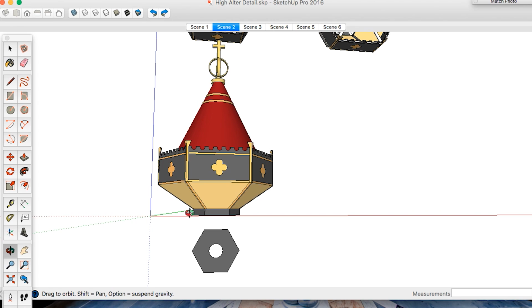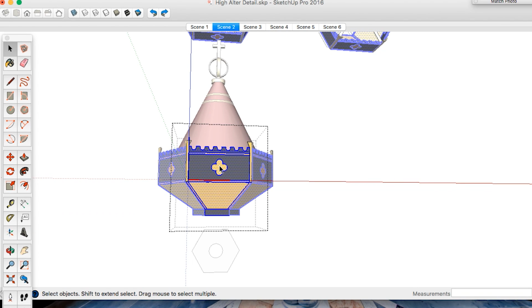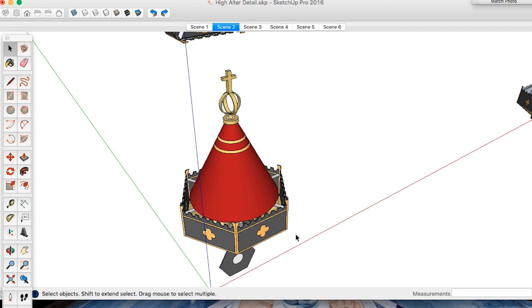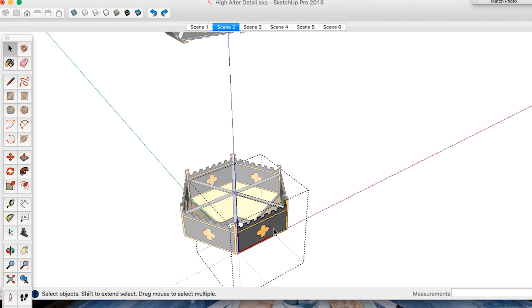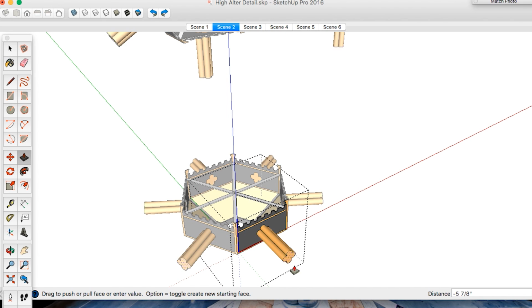As we created this, it certainly wasn't the first version of this. A lot of times we'll take this as a start and just move and copy and make unique, move and copy and make unique. That way you have 5 or 6 different versions, and then you can select the one that works. In this, we were messing around a lot with the quatrefoil and really how thick this was. So if we made this a component, it's doing it to all of the pieces here. But then more importantly, you'll see each one of these sections here will react because they're also components as well.